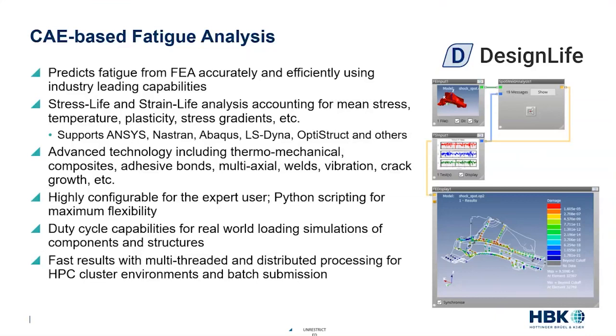And as a system, it's very configurable. It is in its own right a process. And so you could open up a process inside DesignLife and have it already configured for you to be basically drag and drop. But you can also go in and customize it to a very high degree. And so it has a lot of capability there. And then its major strength, and this is typical of CAE-based fatigue tools, is its ability to synthesize the stress histories your part will see. When we talk about fatigue, we're not talking about max stresses. We're talking about the entire load history that a part is going to see over its life. And DesignLife has a wide range of capability to synthesize pieces of FE stress results into these histories. So it's an efficient solution.